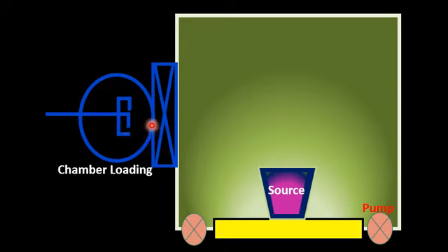In case we want to deposit a multi-component system, then we can flip and introduce the chamber loaded source material as well, in the presence of the source material which is in the crucible of the MBE. So please note, student, that the source material inside the reaction chamber of the molecular beam epitaxy is introduced before creating the vacuum pressure inside the reaction chamber.